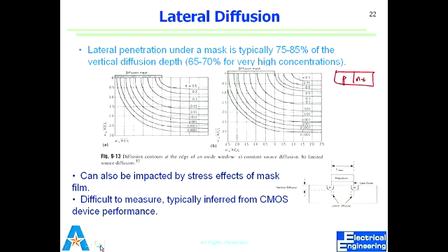But the good thing about ion implantation, it can be done at relatively low temperature. So you can use even photoresist as a mask in ion implantation, which you cannot do for diffusion. Why is that? High temperature. That will just burn away. That we call burning away as ashing.